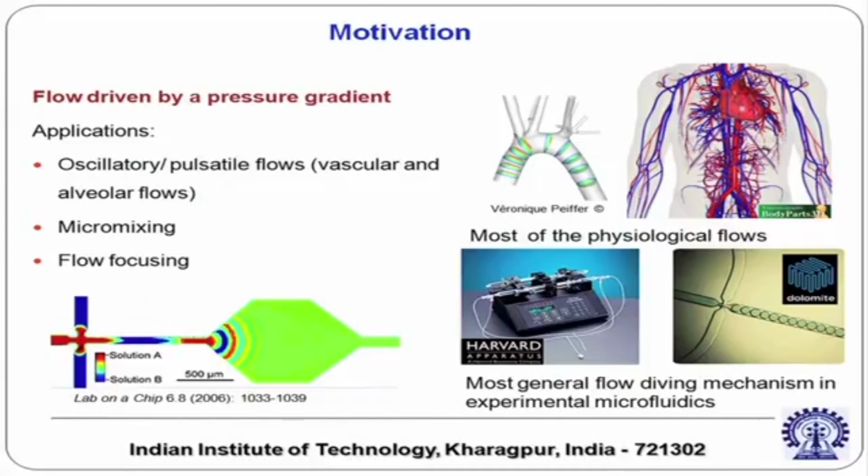So that is one way in which you can achieve good mixing in a microfluidic system, where achieving mixing is otherwise a very difficult proposition because the Reynolds number is pretty low. We will see what the consequence of Reynolds number in microfluidics is, and the corresponding hydrodynamics in many cases is classically known as lower Reynolds number hydrodynamics.